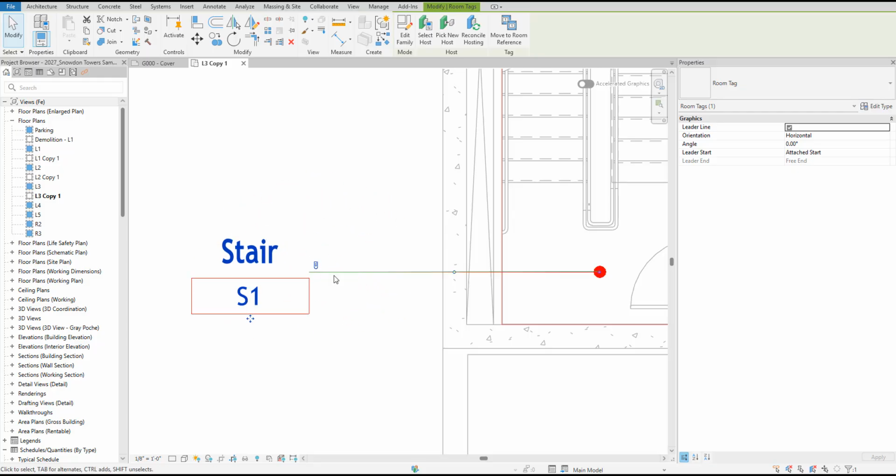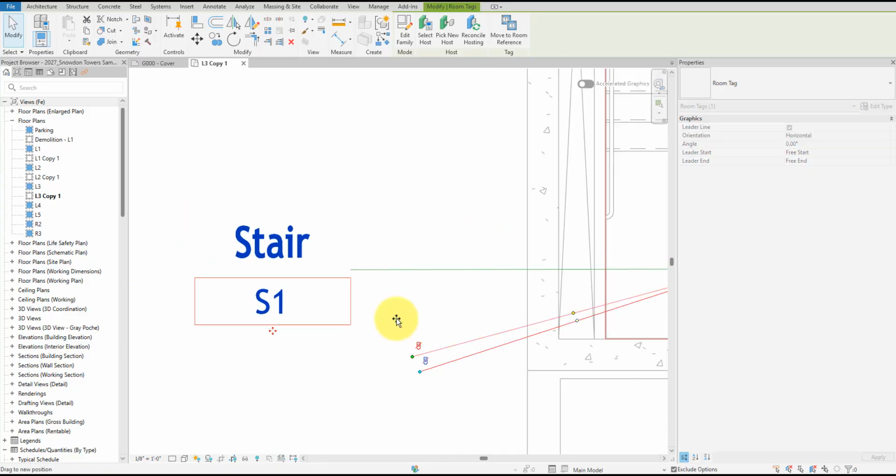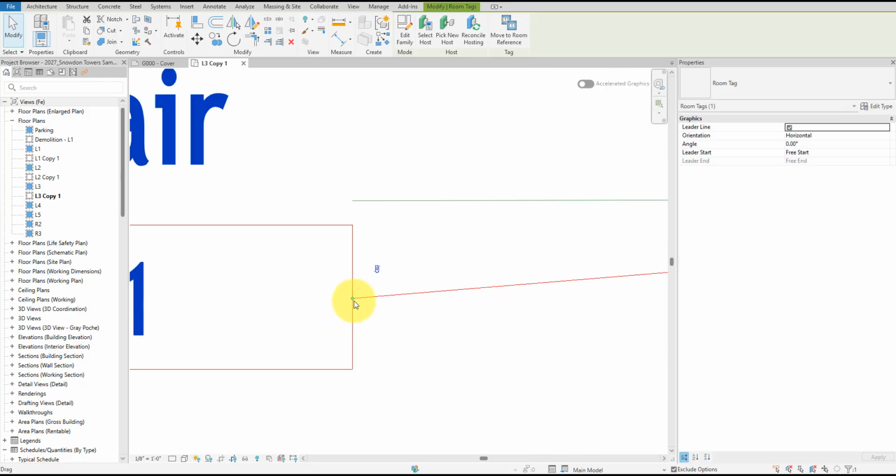By default, the start point is clipped, which means it will follow and snap to the midpoints of the bounding box edges. What I want to do now is click on the clip icon to unclip the start point. This then allows me to freely track this point to any other location without any constraints. Anyway, I want to place the point exactly on one of the corners of this rectangle here. Unfortunately, as you can see here, it doesn't really snap to those edges of the rectangle.